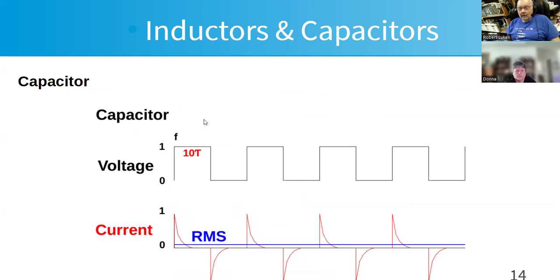So we'll do the same thing. We'll use the same starting frequency, and you'll see we have an extremely high initial current because a capacitor that doesn't have any charge looks like a short circuit, like an empty tank. So you have a high current initially, and as it starts charging up, the current drops. When the voltage goes back to zero, we start discharging it. So you have a high discharge current, and it drops till it gets back to zero.